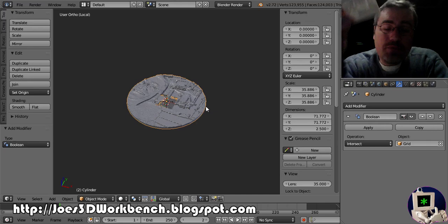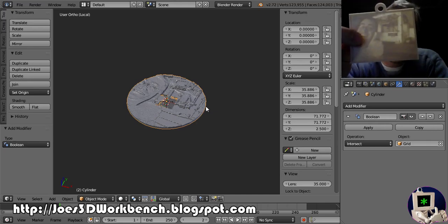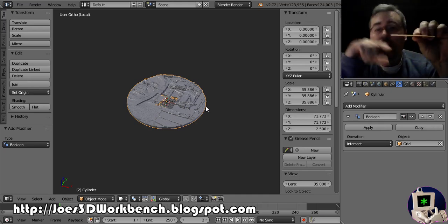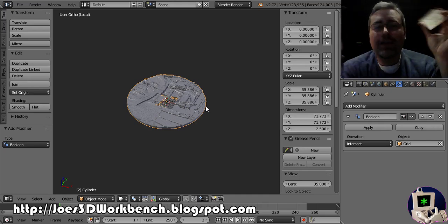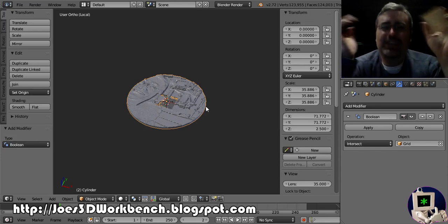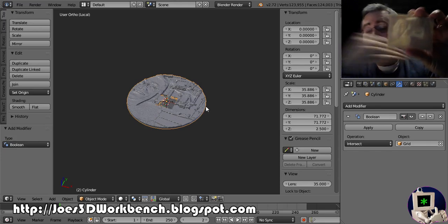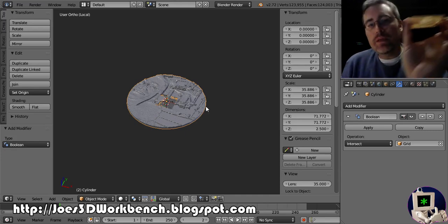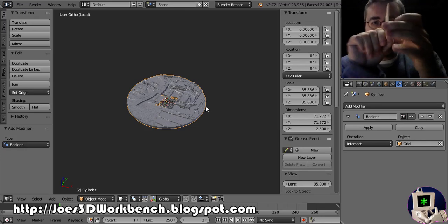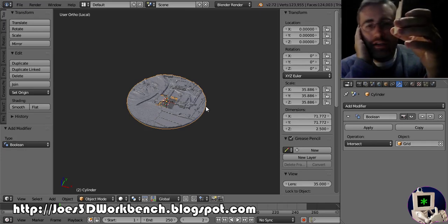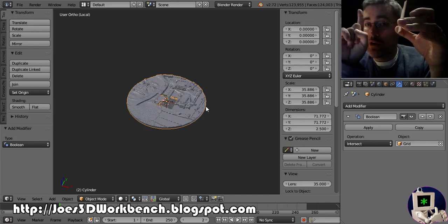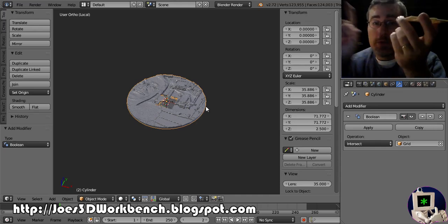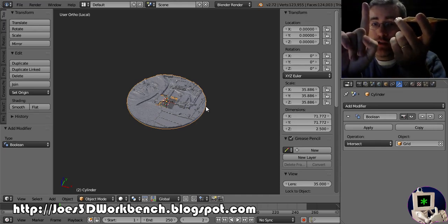I also recommend that when you 3D print these, you 3D print these laying down. Now, that means that depending on your layer resolution, you're only going to get maybe 16 or 20 color layers out of it, because every time it does a layer, that's as much color as it can do. Some people try to print them vertically because they think that they can get more detail with them. And if you do that, use only one shell and 100% infill. In fact, if you lay it down, I recommend one shell, 100% infill.